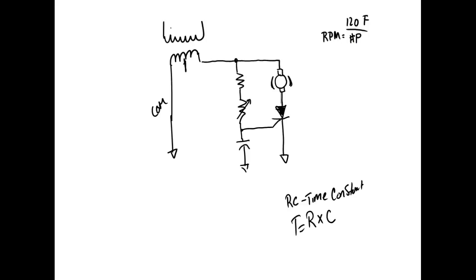So what happens on an AC motor is that if you reduce the voltage to it, it doesn't produce the horsepower and it will stop. If you put too much voltage on it, then it's going to burn up. And of course, if the motor stalls and we don't protect it, it'll burn up. So what we do with an AC motor, we've got two options.